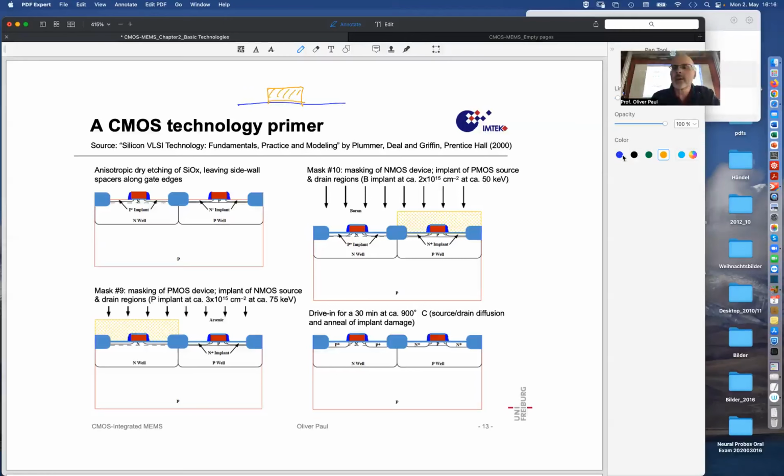Anyway, so here's a gate, and then there is this protection layer, this conformal layer that looks something like this. And now, if we did an isotropic etching from all the sides, we would remove, so I'm drawing this on one side, we would remove a layer, and another layer, and more layers, and at the end, just as this was conformally deposited, it would be conformally removed, and nothing would be left.